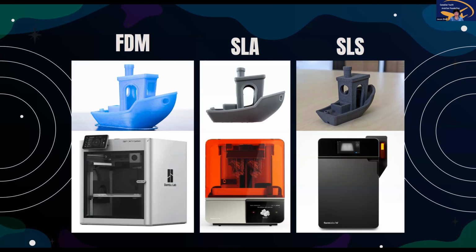And the final type of 3D printer we're going to talk about is an SLS machine. So FDM uses plastic, SLS uses a type of powder. So how that works is that you put a lot of powder. It's almost like sand, but it's like a plastic powder. There's lasers inside that shine at a certain point, and once it shines at that point, it becomes a solid. So with SLS, you can make a lot of different shapes. You have a lot of flexibility in the shapes you can make because the powder allows it to print basically whatever shape you want without needing supports.